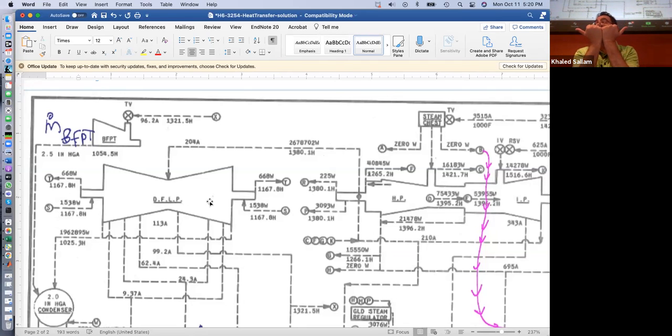Why? To balance the axial force. Because the thrust bearing, if it has axial force, you probably have studied this in machine design too. The axial bearing is like horrible. You want the bearing to have very small axial force. So that's why also the high pressure turbine and low pressure turbine are sitting back to back. It's not the same, but they are trying to balance it, so that the whole shaft is not under severe axial force.